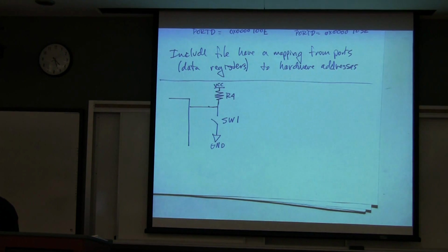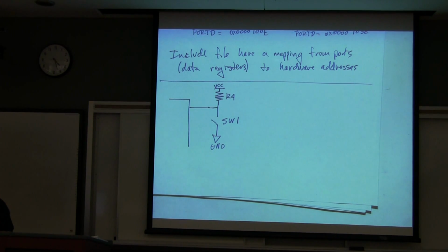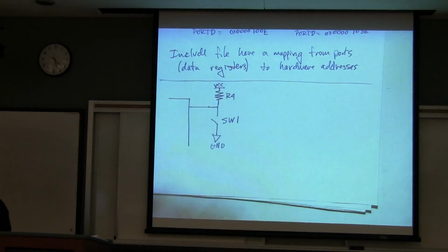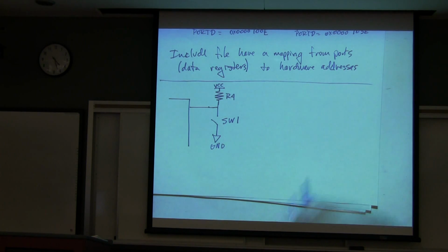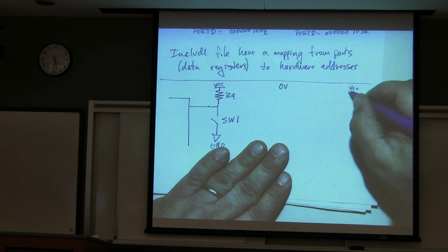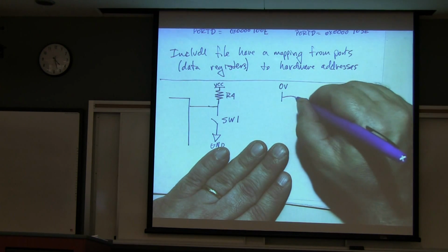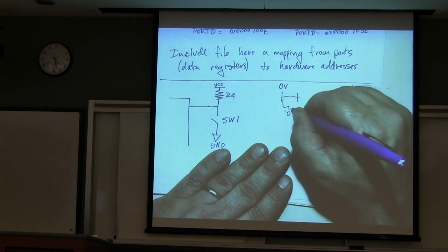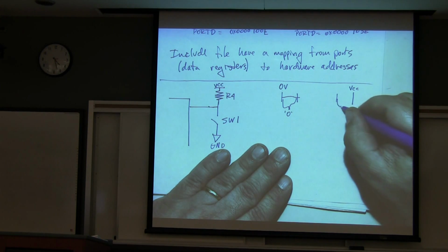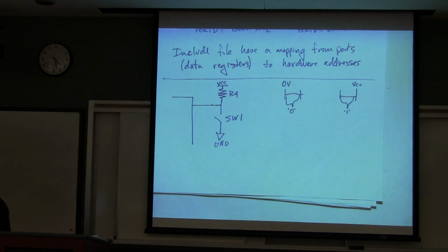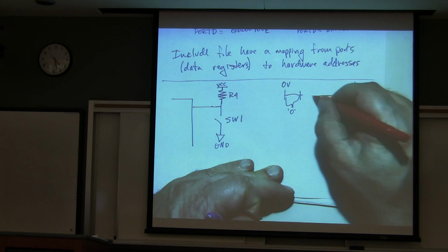And this big resistor will have some sort of value which will ensure that you don't have much current that you're wasting between here and here. But it will be as close to VCC as possible. Because as you can imagine, our microcontroller is going to be looking for 0 volts, and it'll be looking for VCC, and it'll probably expect a little bit above here for logical 0. And right near VCC, it'll probably accept a little range there for 1. And then there's this no man's land in here that you really don't want to reside in.